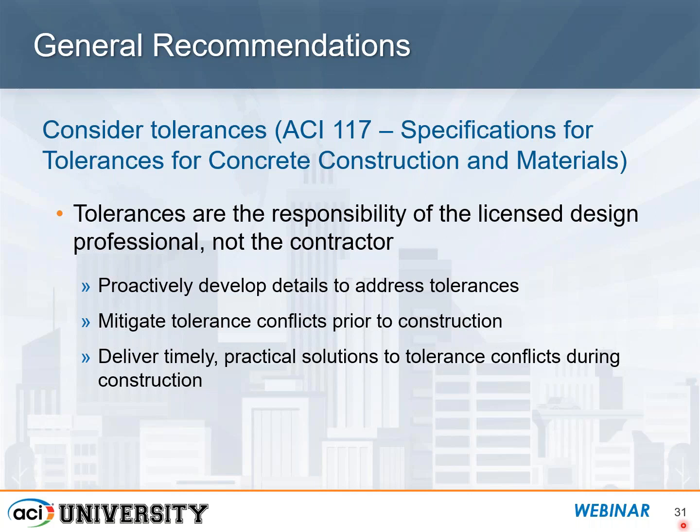Having to move the reinforcing steel, especially if it's in a pre-assembled cage, is going to waste a lot of time and a lot of cost as well to try to make things work. So if you can change the formwork and alleviate the problem that way, that's usually the most cost-effective thing to do. And we'll get into tolerances a little later today.